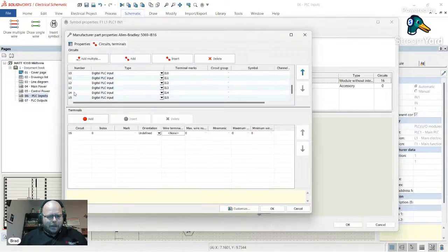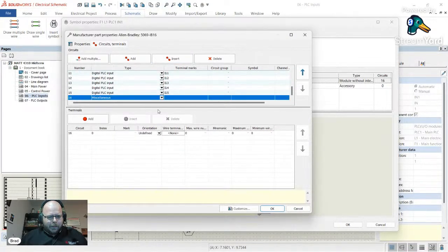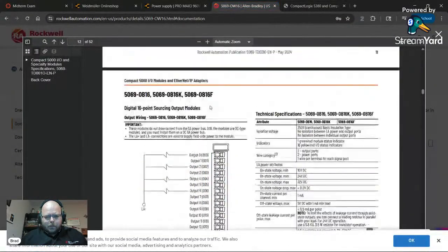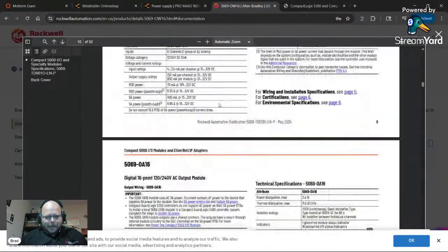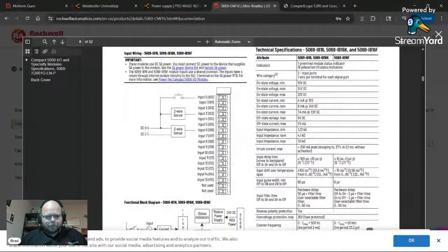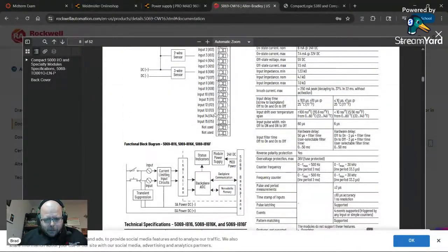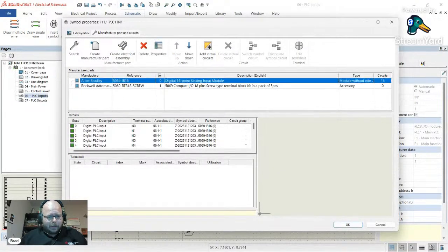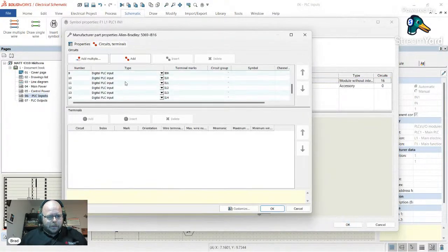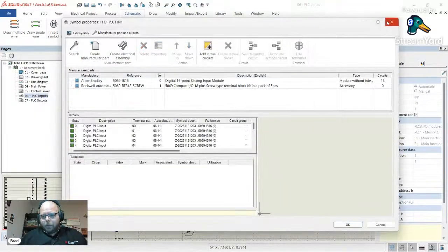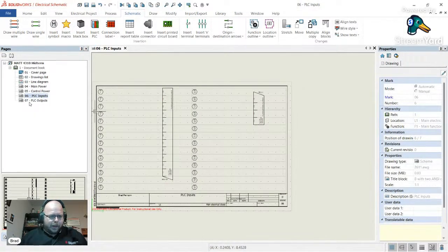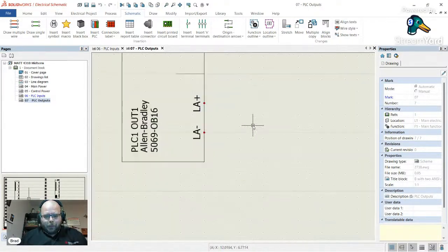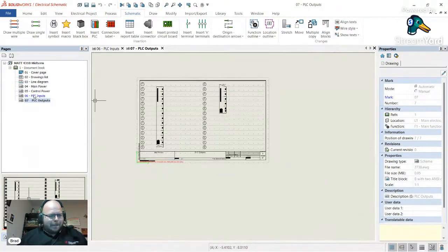Let's add, and I did a miscellaneous, and I want that. So the IW, or I want the IB 16, just to see. Okay, they're not actually used, so I don't need that. Never mind. Did it actually add that? I hope it didn't, because I didn't accept it. Okay. So yeah, we're not using those last two terminals. So the inputs are correct. The outputs has to have a power supply, so you need to power the outputs. So bear that in mind.